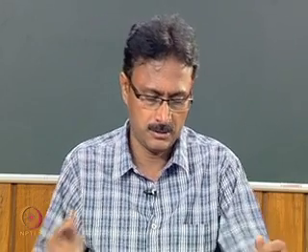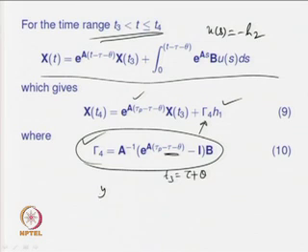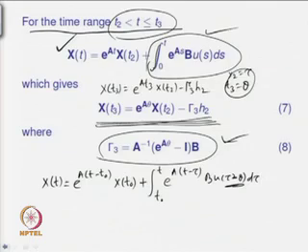We have been able to find state equations for different time ranges associated with the output signal. Once the state equations have been found, it is not difficult to get the output for the whole one period of the sustained oscillatory output using the simple equation that y(t) is given as c x(t). Keep in mind the equation numbers, what are the important equations for us for different segments.